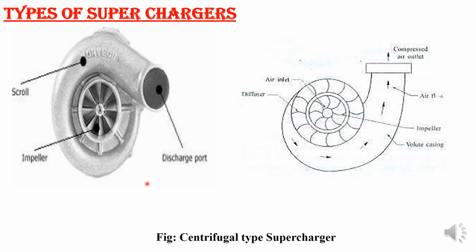Okay. Then the centrifugal compressor is simple in nature when compared to reciprocating. It is a small case, not bulky in nature, very small, cheap also, and has good efficiency in the pressure ratio range of 1.5 to 2, which is commonly used for supercharging.